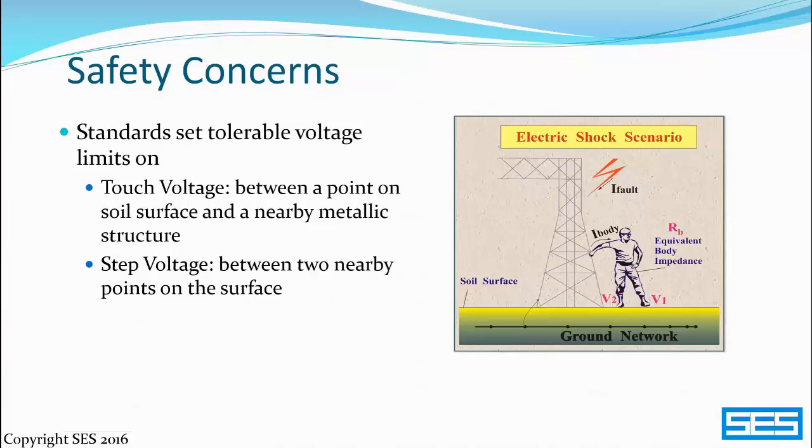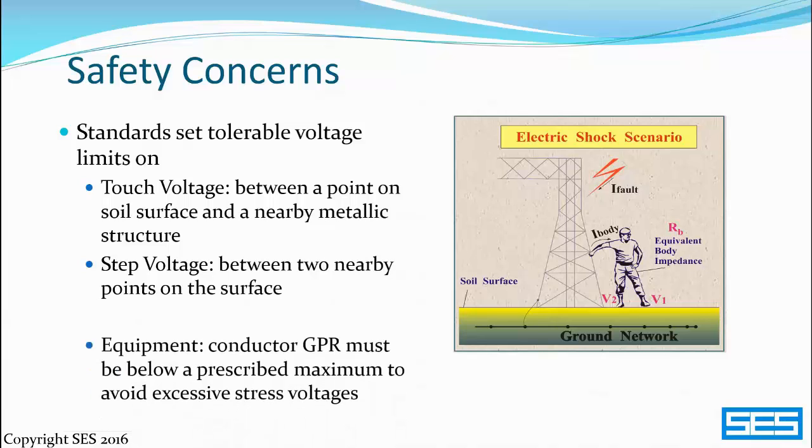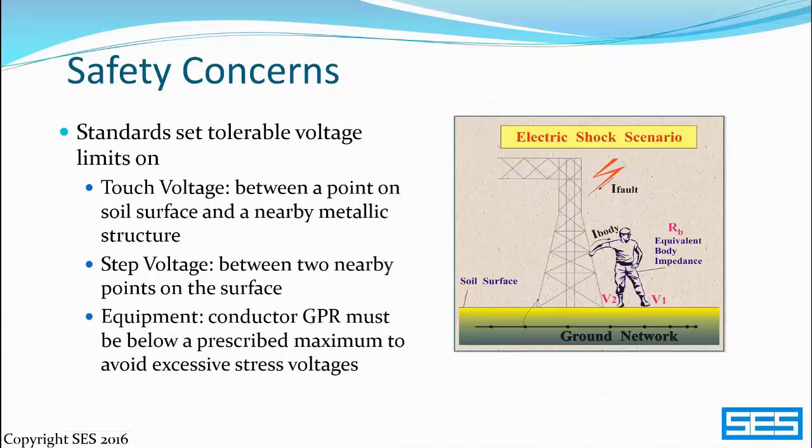Step voltage is defined as the voltage between two points on the surface of the soil, say V1 and V2, at some maximum separation distance, usually around 1 meter. For equipment integrity, it may also be necessary to keep the voltage with respect to remote earth, the GPR or ground potential rise, below some given value to avoid problematic stress voltages.